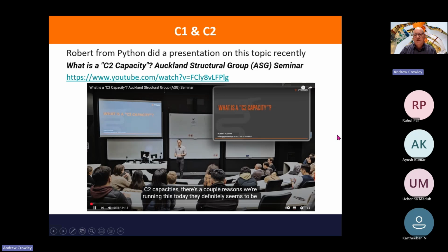There's a chap from Python called Robert who did a presentation to the Auckland Structural Group, I think it was last year or the year before, and that's available on YouTube, and he goes into much more detail about what is C2 and C1 capacity, because all of these C1, C2 capacities have been aimed at anchors in beams, not really foundations, and he points out what's a beam and what's not a beam. And so by extrapolating on the design of anchors in beams, you might be a little bit over conservative in foundations.